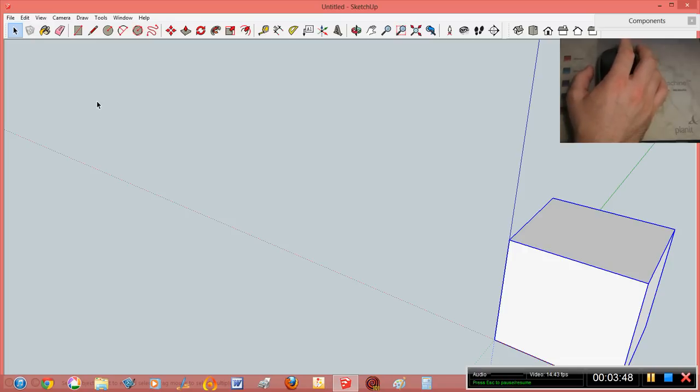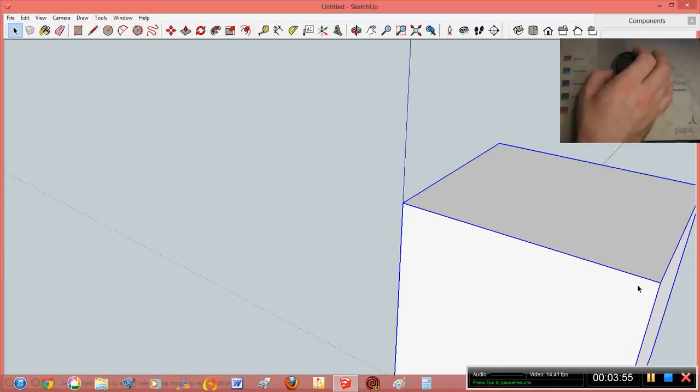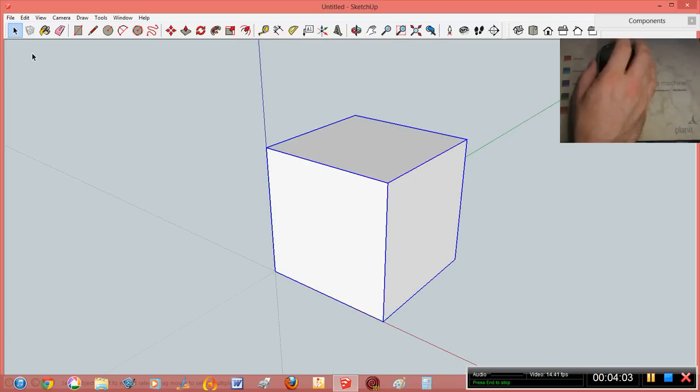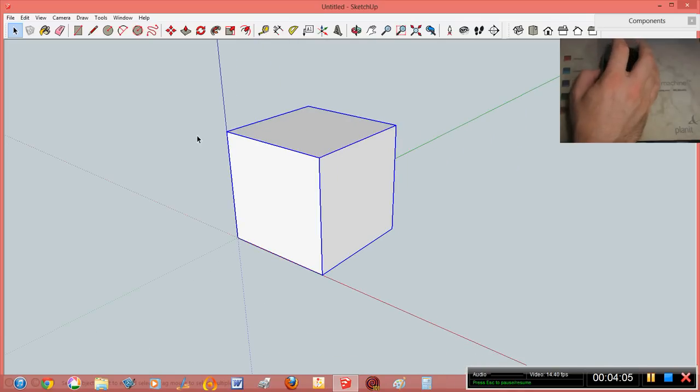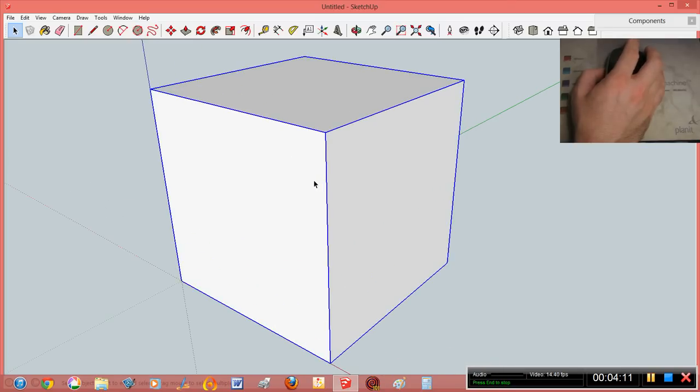And what I mean by that is, if I want to see in more detail this bottom right corner, I can zoom on it, but I want to see the even further bottom right on this block. Well, what I would do is go to the top left corner of your drawing and zoom out. And that brings this more into focus. And then move my cursor over the box and zoom in. So wherever my cursor is, that's where the focus of your zooming in or out is going to be.